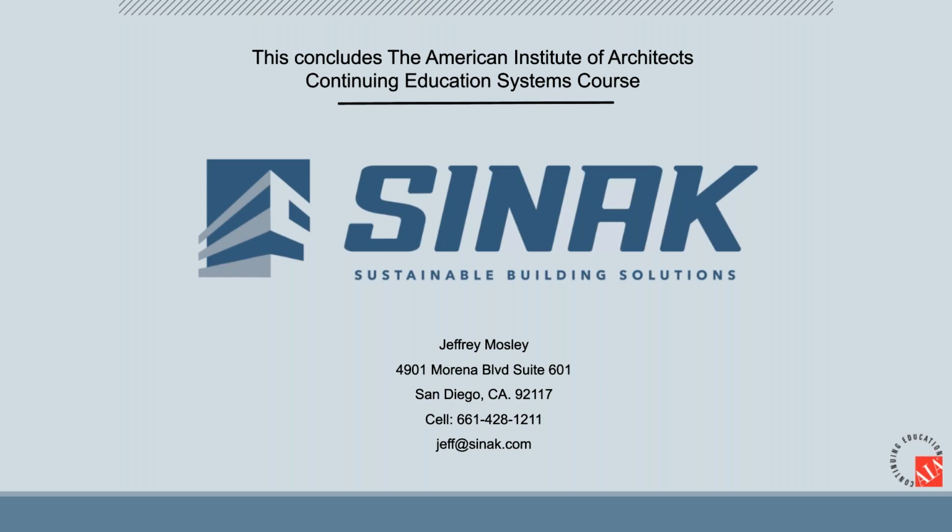Oh, that's a great one. Because ASTM has a hierarchy of acceptance by equal or better than, I would do a submittal package referencing the existing specification section and subsection, and then I would note the performance criteria of the spec. Now, here's what I mean. If a 309 product is specified, that is using an ASTM specification that has a performance criteria of 0.55 kilograms per meter squared. That is under ASTM C156. The intent of this specification is to control moisture loss, not make a shiny acrylic resin sit on the surface. So you would submit a performance-based substitution request.